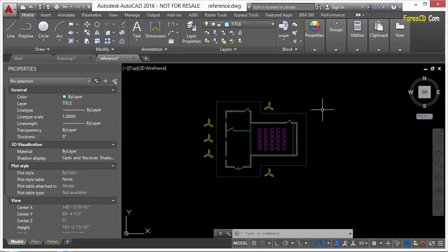Now, let's say a residential design needs a survey drawing to establish the legally defined property boundaries. You can have a surveyor create that drawing and then you xref it in. You also need an architect to create drawings for your home or the building, whatever that might be. Now, that other person can make those drawings. And when you get that, you can xref it in.